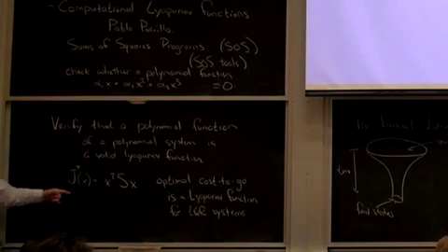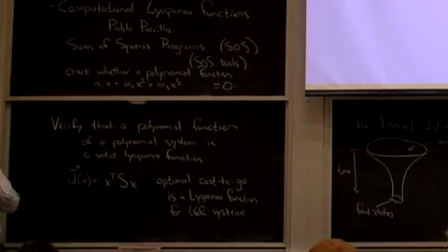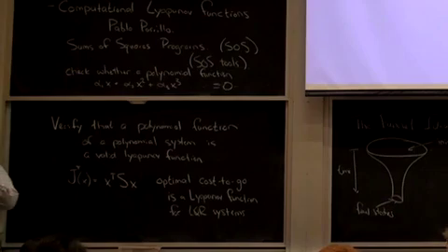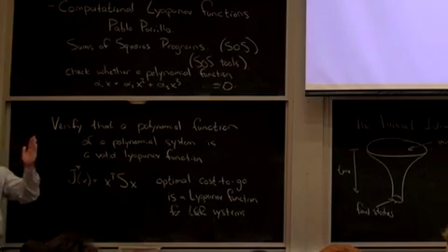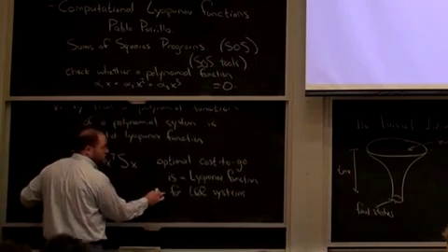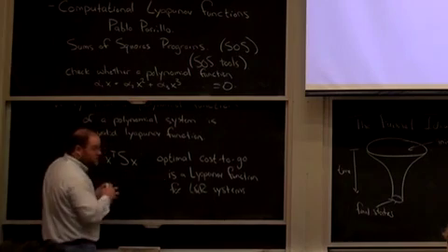Okay. If I have a nonlinear system where I've linearized it and done LQR control, then I expect this function to be a Lyapunov function over some domain where the linearization was good, and eventually to no longer have this nice negative definiteness property. Does that make sense? The optimal cost to go from LQR isn't a Lyapunov function for the entire state.